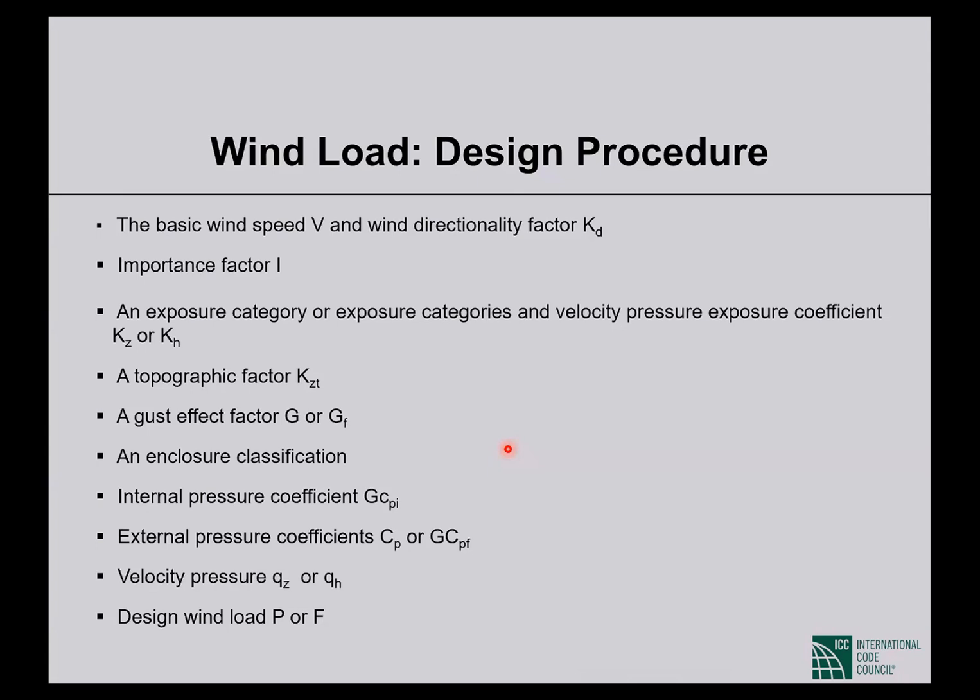That is an advantage for design engineers, that you can blindly use the available software. You have to just select ASCE 7-05 code for load calculation in the drop-down menu of your software. That will take care of everything, but you have to be aware of the steps and many details.